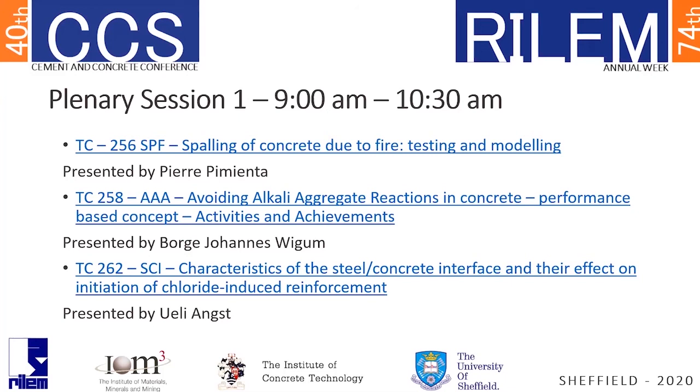Of course, if you do tests with a metal in a solution, the pH turns out to be one of the major influencing factors. But as soon as the steel is embedded in concrete, which is very different from a solution, because we have solid phases present, we have voids present. The voids may be water filled, they may be gas filled, and so on. So it's a completely different situation.